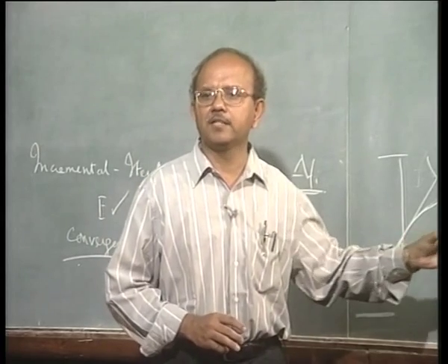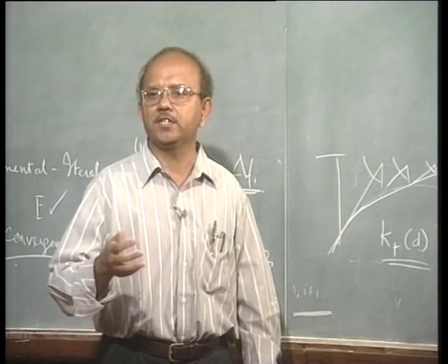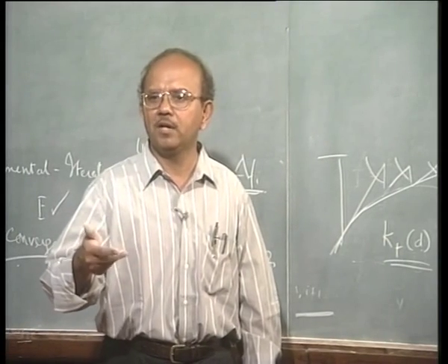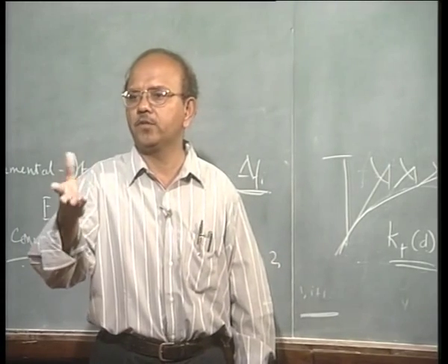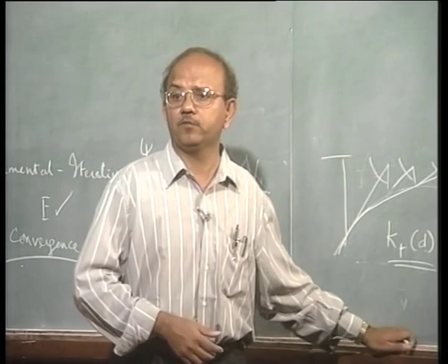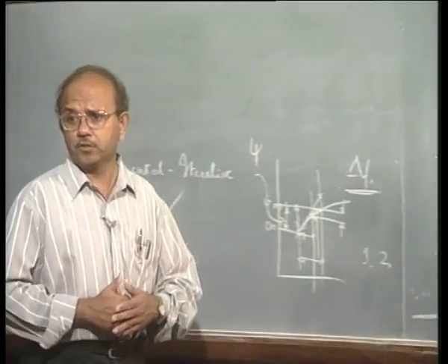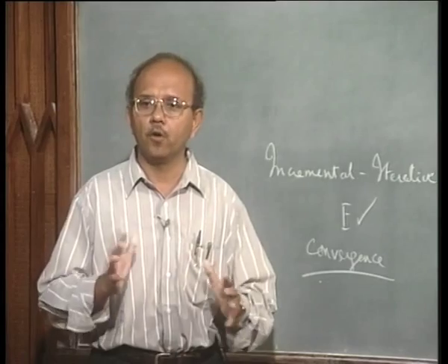In contact analysis also this is exactly followed, because there also the penetrations have to be made 0, and hence every time you calculate the forces, you see that there is no penetration or that the calculated forces are in equilibrium with the applied forces and so on, and hence this kind of approach is what is followed.